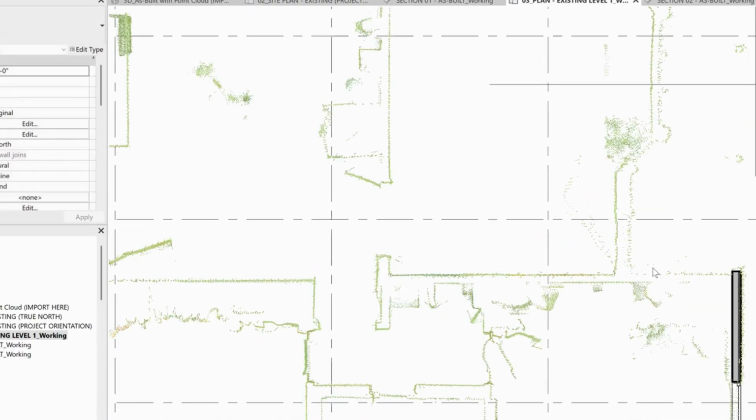So anything that I draw, I mean, this is Revit, so I can draw a line, I can do a measurement here. In Revit, there's a measurement tool, measure between two references. And anywhere that I click on, you can see the dimension on the screen. You see it? Where it says 11 feet. Yeah. Everything here is in complete 100% full scale. The point cloud comes in at 1-to-1 scale.